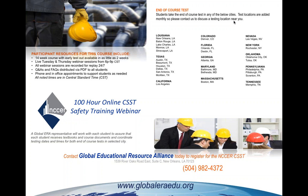It's really imperative that people know the emergency stop signal. I think all employees in that area should be trained on it. Further, a crane operator always has the right to not initiate and not take a load, but also OSHA requires that a crane operator always stop work regardless of who calls a stop in the crane area. So learn the crane signals if possible, like we were just talking about.